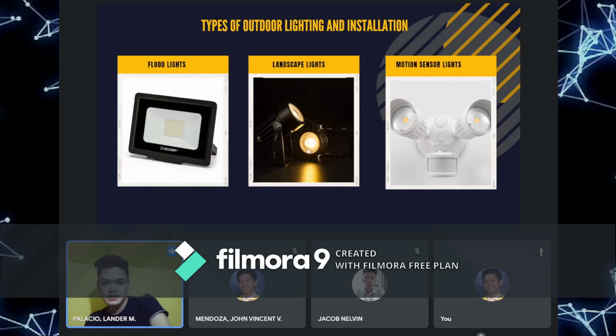And according din sa PEC, we should position the lamp and detector far apart so heat from the lamp doesn't set off the sensor. So kailangan natin yung lamp at saka yung detector should be set apart kasi yung init na nanggagaling sa lamp or dyan sa bumbilya na yan is maaaring makapag-set off dun sa sensor niya.